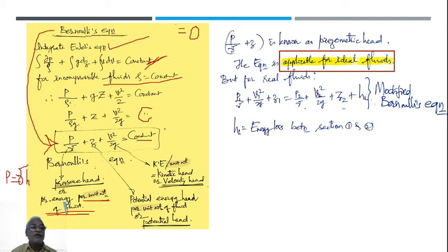What is the meaning of constant? Means if the flow is occurring like that, and then if you consider energy of flow per unit weight at a particular point, and then if you go further at some distance and then pick up fluid and measure the energy per unit weight, it is not changing, it is remaining the same. That is what is constant, right? It remains same, there is no change, the total energy remains same. So it is nothing but conservation of energy principle, in short, right? The form is different so that it is applicable for fluids.